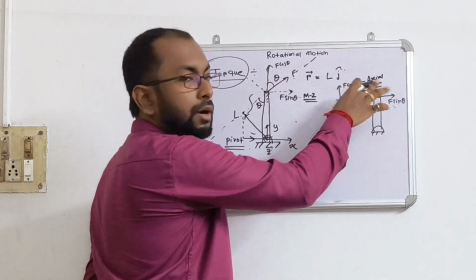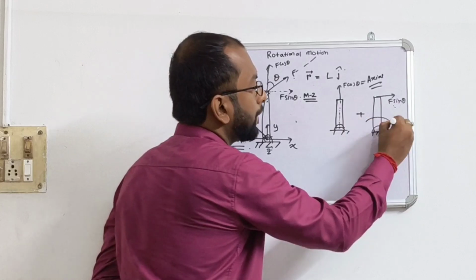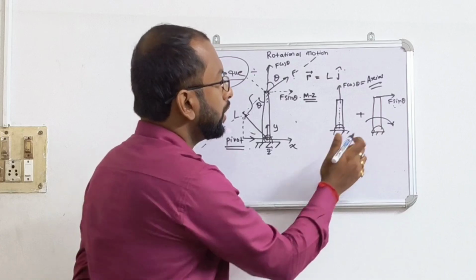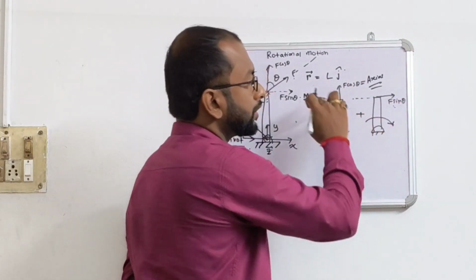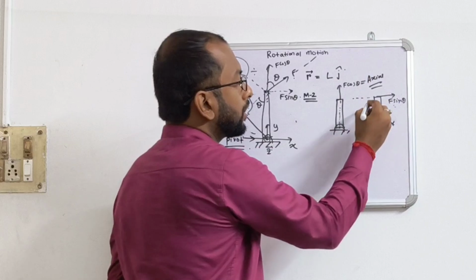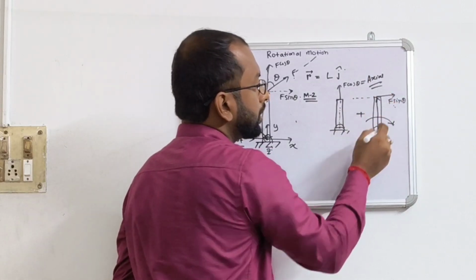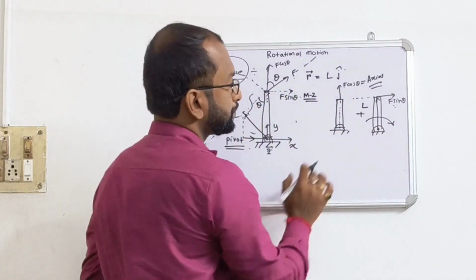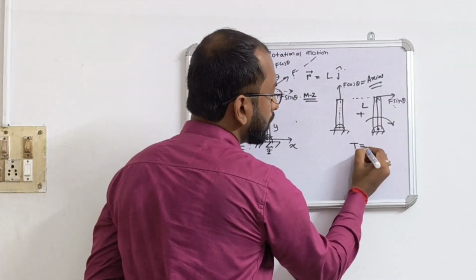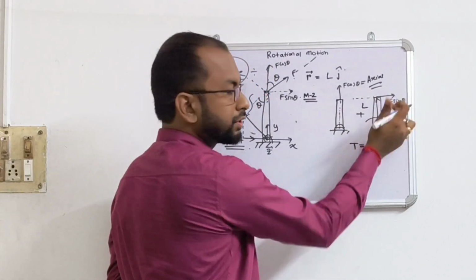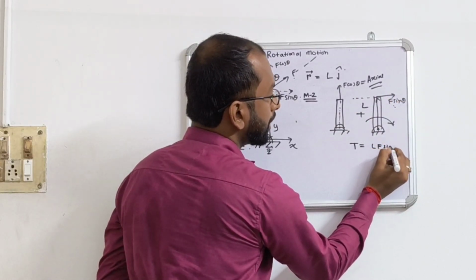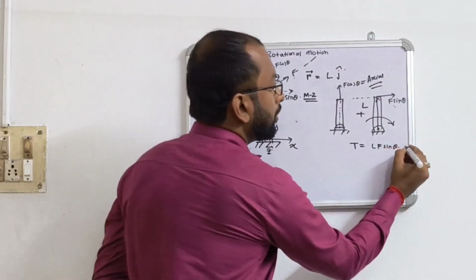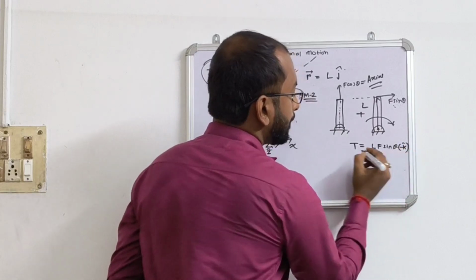But this component of the force F is able to rotate the body in the clockwise direction, as we discussed in method 1. Now the direction of application of the force is this one, horizontally. If I draw perpendicular, then the direction is this one. So the distance will be L only. L is the length of the rod. So we can directly find out the torque by multiplying the perpendicular distance into the force. So L into F sin theta we can write. And again this is rotating in clockwise direction, so the vector will be minus k cap. So this is the torque.